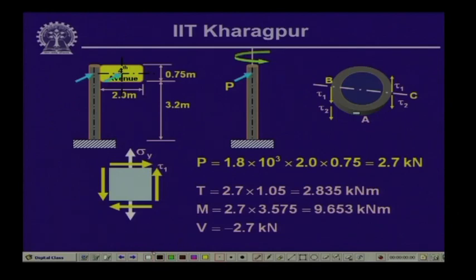Now, you see the analysis of this particular loading action is indicated over here: the resultant load is acting at the CG of this particular board, and this load is transferred to the vertical axis of the member, and this is the load P along with a twisting moment, and that is what is indicated over here. Now, this vertical post is subjected to a concentrated load P. Now, what are the distances? This distance is 2 meter, and the diameter of the tube is 100 millimeter.